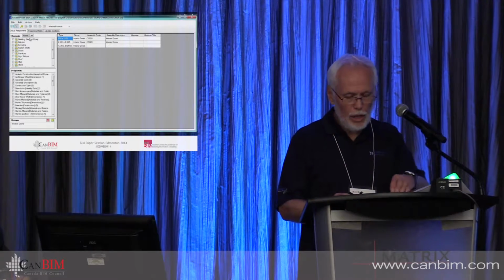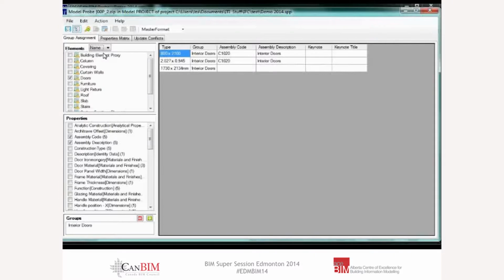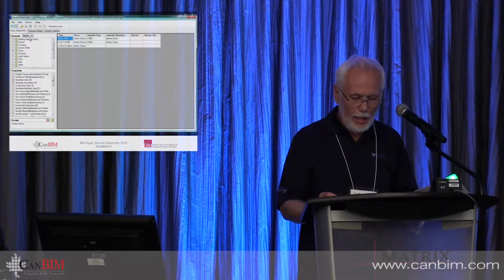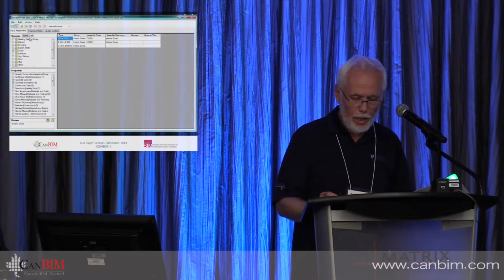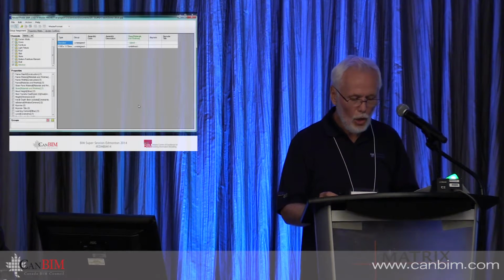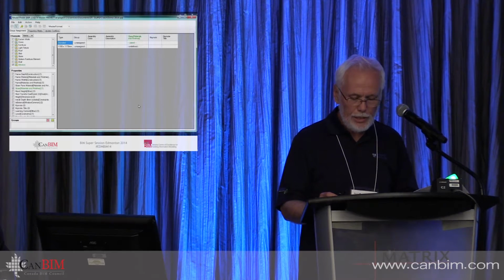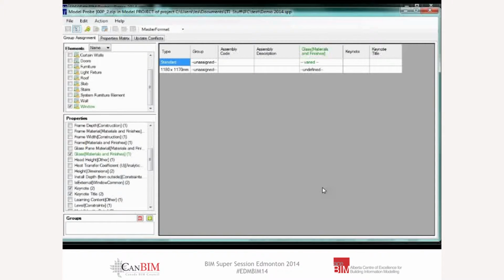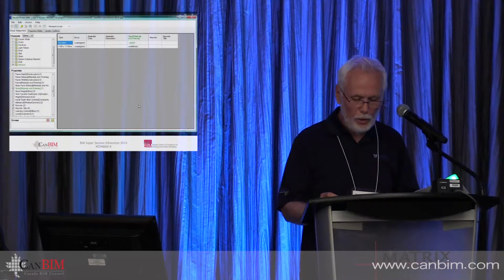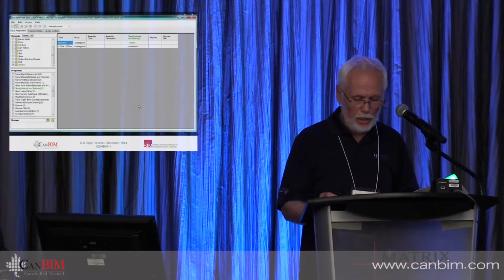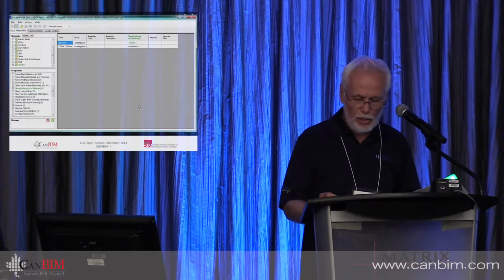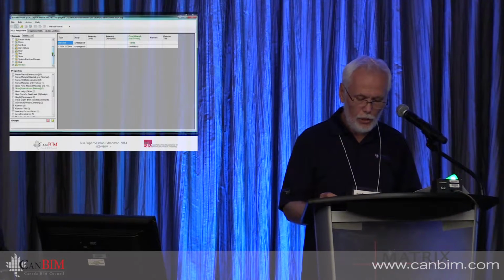A model is never static during the design process, so Spec Edit allows the specifier to import an updated version of the model. Any changes in the model are color-coded in the display so that it is easy to see what changes happened. In this example, I changed the glazing material in one of the windows so that the category windows is highlighted in green along with the glass property, and in the table you can see the value that changed in the update.